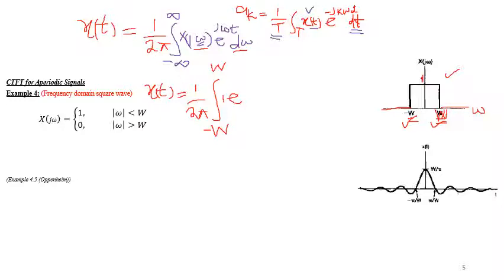And I hope you don't forget the convolution identity. The identity of convolution is the impulse, right? So if you convolve anything with the impulse, you get the same thing. If the impulse is scaled, the resulting signal will be scaled by the same factor. If the impulse is shifted, the resulting signal will be shifted.